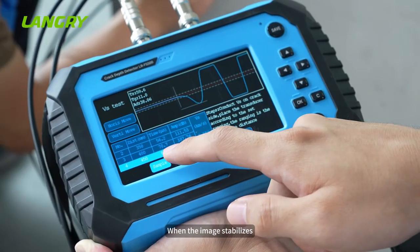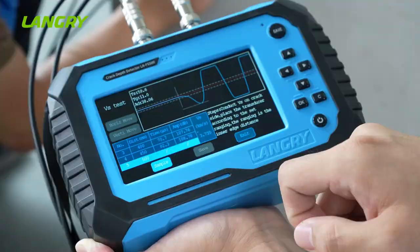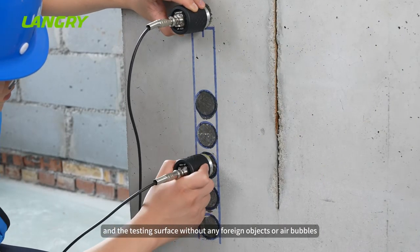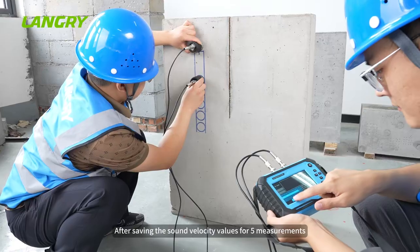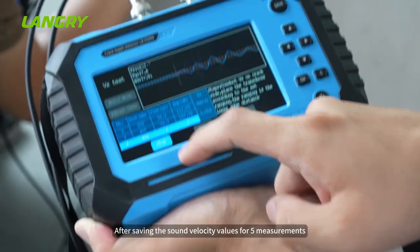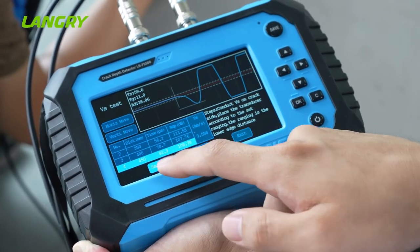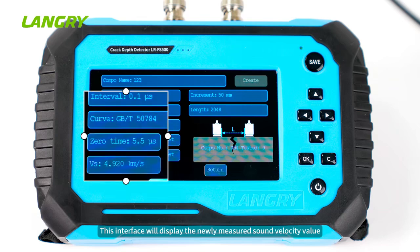When the image stabilizes, click Save to save the value from the first measurement, ensuring good coupling between the transducer and the testing surface without any foreign objects or air bubbles. After saving the sound velocity values for 5 measurements, click Sample to return to the previous interface. This interface will display the newly measured sound velocity value.